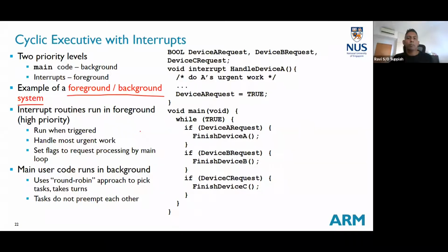Okay, so you can still have some real-time processing, but your interrupts, as we have seen before in EPP2 as well, you should keep very short and compact to do what is really important, and the backend processing of information should be left to other tasks or other functions. Because if you get stuck in an interrupt for too long, then you will hold up your main loop. So that also affects the dynamics of the system. So you want to keep your interrupt short and simple and leave the rest to background processing.